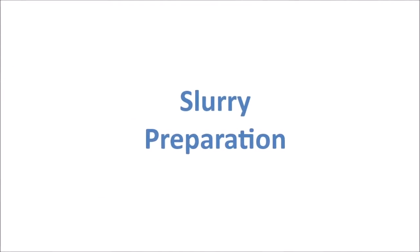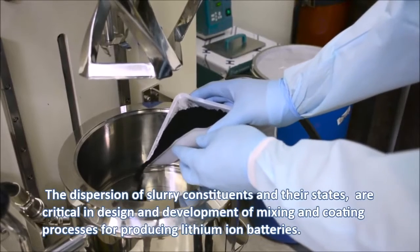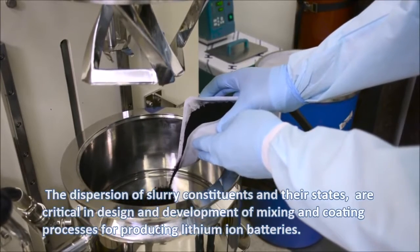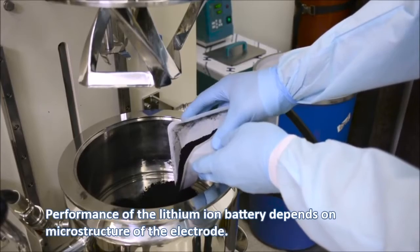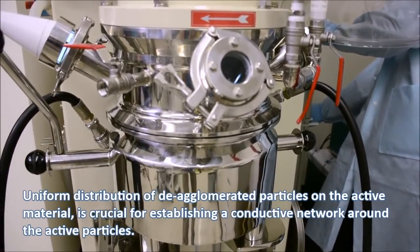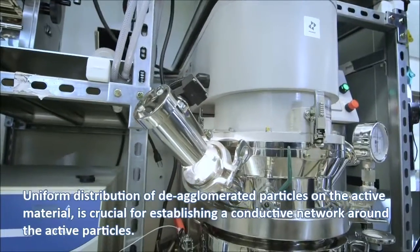Step 1, slurry preparation. The dispersion of slurry constituents and their states are critical in design and development of mixing and coating processes for producing lithium-ion batteries. Performance of the lithium-ion battery depends on microstructure of the electrode. Uniform distribution of the agglomerated particles on the active material is crucial for establishing a conductive network around the active particles.